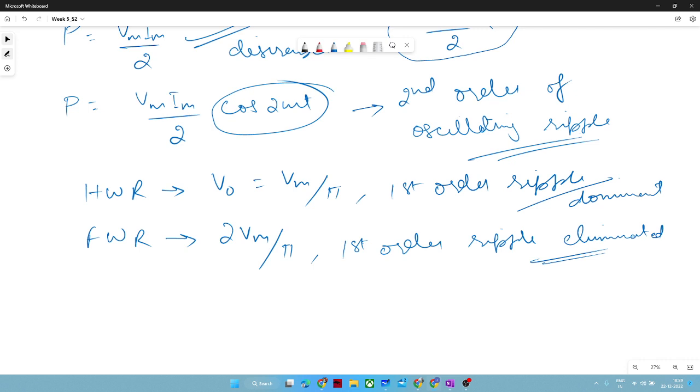But why are we also using the half wave rectifier? Yeah, of course, that is a good question. In the half wave rectifier, you are done with a single switch. You do not need more than a single switch. And switches have some cost, right? That will be the major cost for any power electronics device. Devices have higher cost.